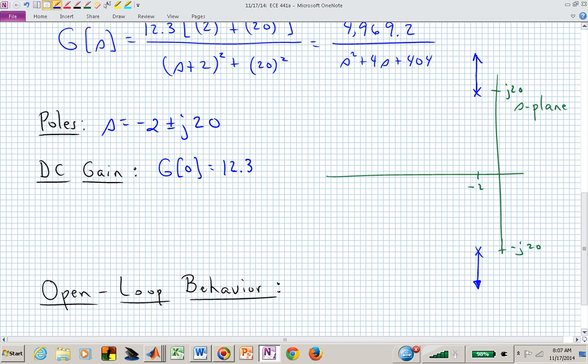What does that do to the settling time if you increase the gain k in this closed loop configuration? Sigma is not changing, is it? So the settling time is not changing. What will happen if you increase the gain k and move along that root locus in the closed loop? What properties of your system will be impacted?